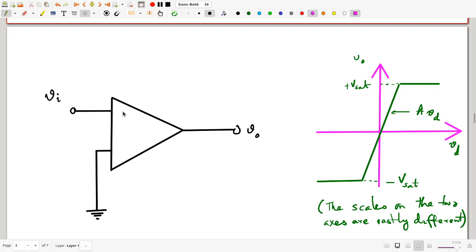But just to emphasize that until we get used to the convention, here we are labeling the inputs directly so that you can see that this lower one is a non-inverting input marked plus and the upper one is the inverting input marked minus. Let me stress once again, if an op-amp comes without the inputs marked, then the upper one is the inverting terminal by convention.